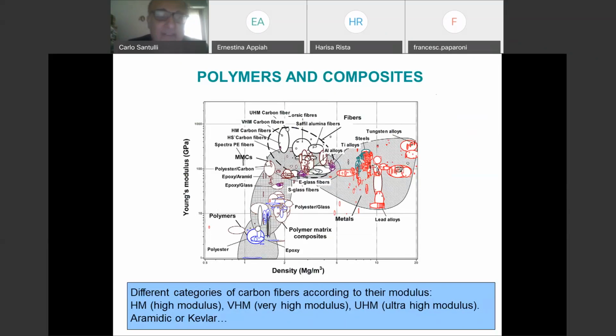So they might have Young's modulus values which are much higher than those for steel. You might have carbon fibers with 700, 800 gigapascal of Young's modulus, which is 4 times more than steel. On the other side, they are brittle, but we put many fibers together into a composite, so it's no longer a question of thinking about brittleness. They still are brittle, but that's the way they work. They absorb also a lot of energy in damage, which is important in some cases.